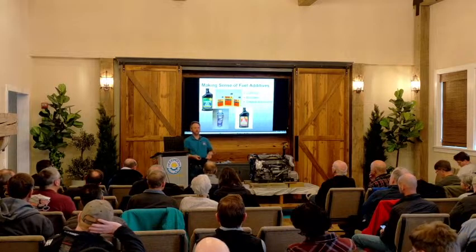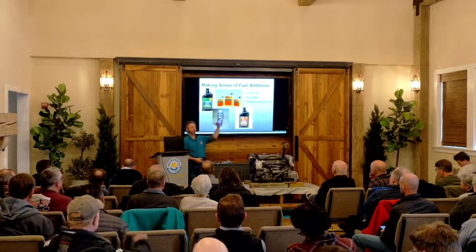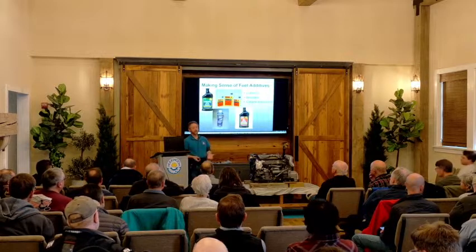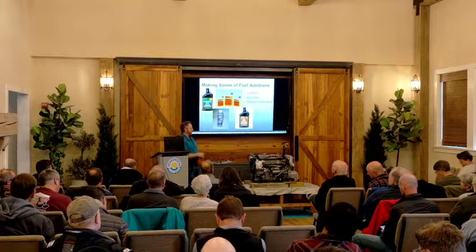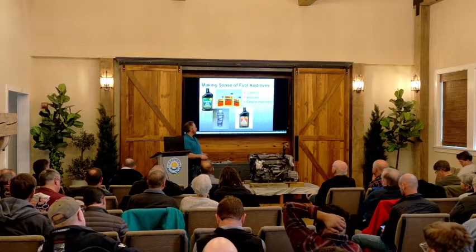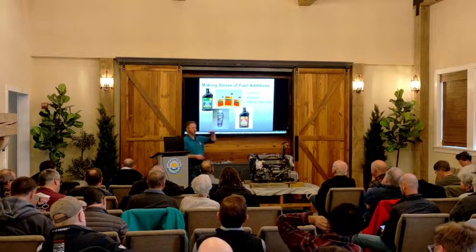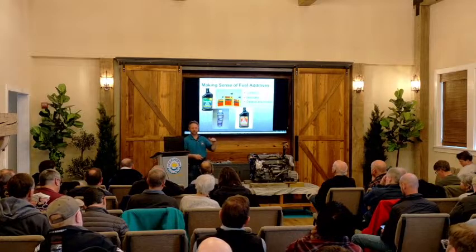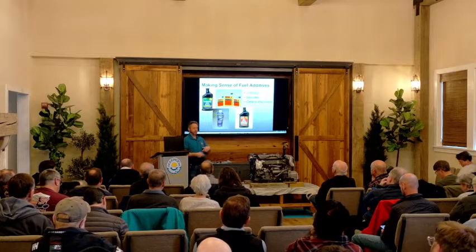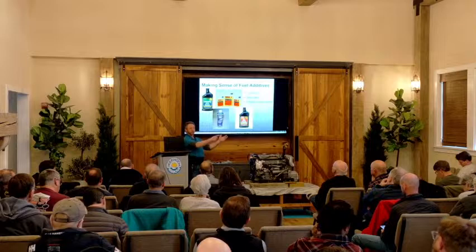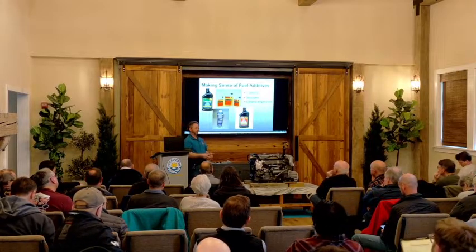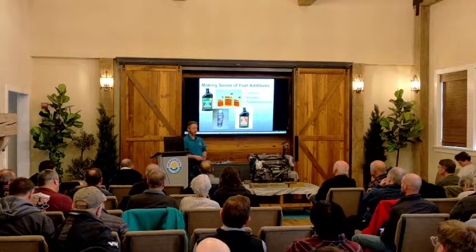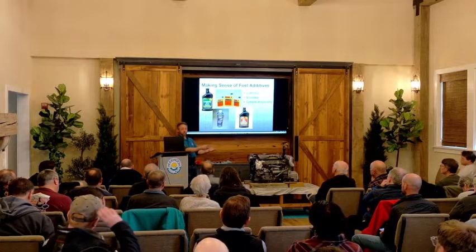So if you're in the market for buying a used boat and it's been on the hard for 3 or 4 years, then you may be concerned with what's going on in that fuel tank as far as the older fuel. So once that cetane rating starts to degrade, that fuel becomes harder and harder to burn. But it will burn, but it may produce blue smoke out the back of the boat because old fuel tries to turn itself back into crude oil if you let it sit long enough. And so that's why it's going to start producing blue smoke.